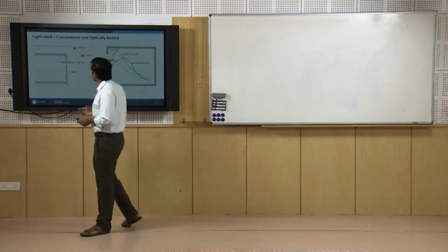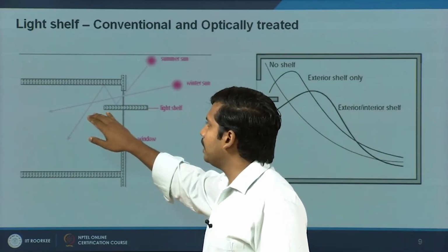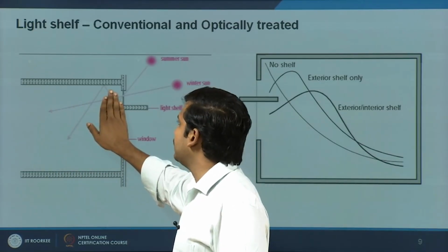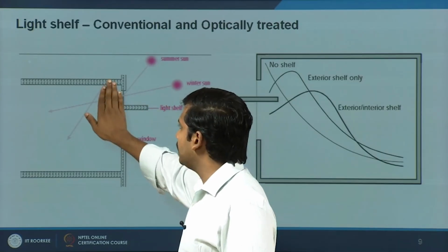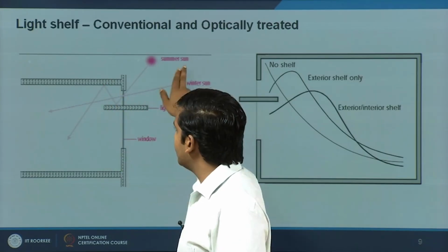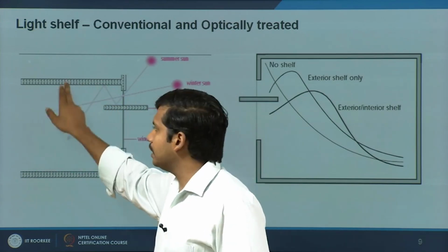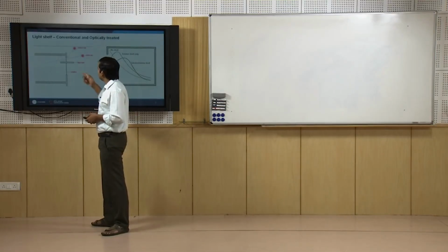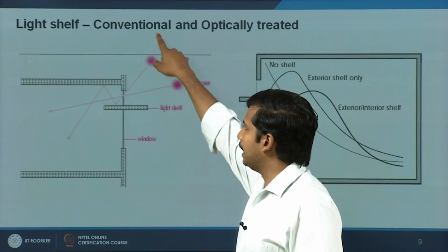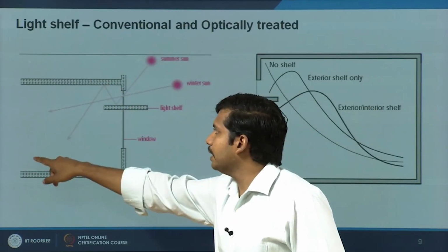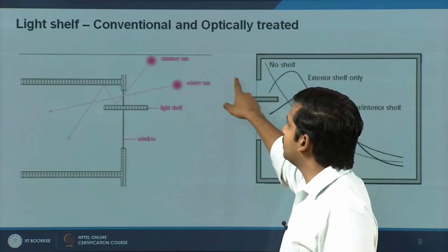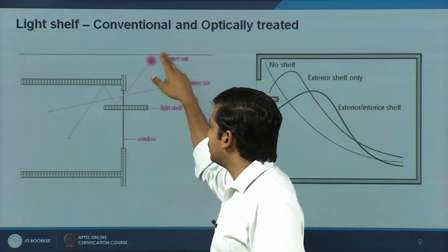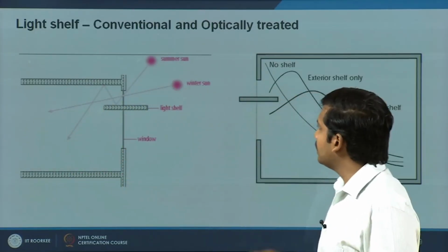It works, as I said, on a simple principle. It can extend into the building. If it extends further, the amount of light penetration will be much higher, whereas if you are closing it up to this, it is a simple shading device where the interior projection is not available, then it will only reflect to specific areas. The further interiors will not be lit very well. Of course, there are other associated things I will talk about in a moment. Summer sun is high, you get light directly into the interiors, not into the core, which is not much lit, whereas winter sun is low and falling directly, you will get direct skylight, whereas summer sun will reflect into the building. There are other considerations.